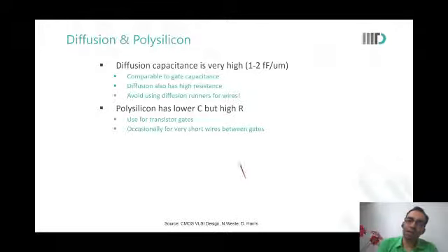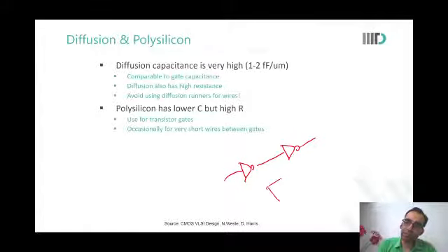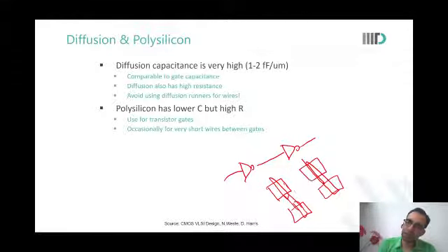So let us say we have an inverter that is driving another inverter. That means there will be a PMOS and an NMOS, and the output of this PMOS and NMOS will go and connect to the poly of this other inverter. Something like this we want to do. You connect them through wires. Now don't go to the diffusion layer and route through diffusion. Route only through metal.